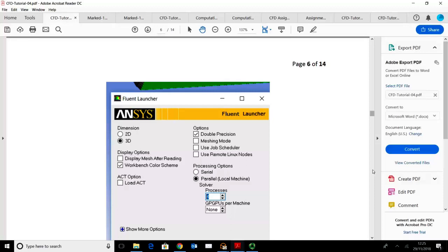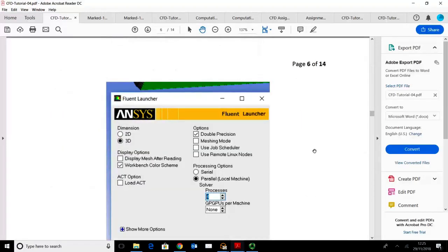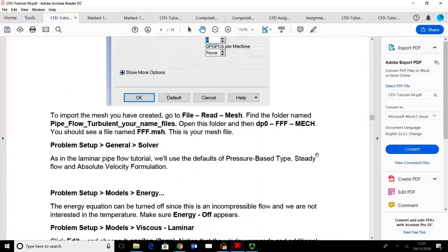If you don't update, you can't see all the meshes that have been created, etc. Okay. And then once you have created the geometry, you go to meshing, you get the mesh, and once you have updated everything, you will see that your mesh has already been created.